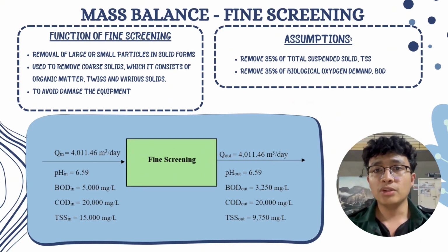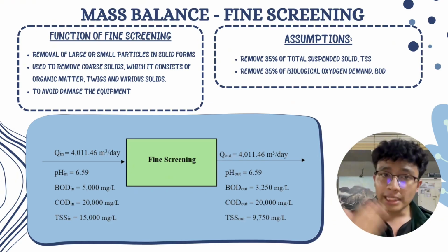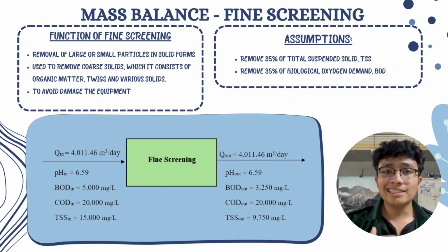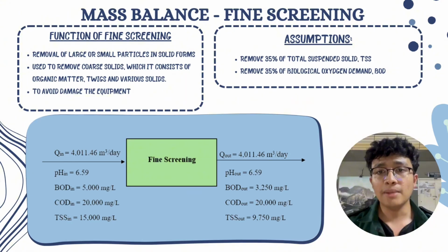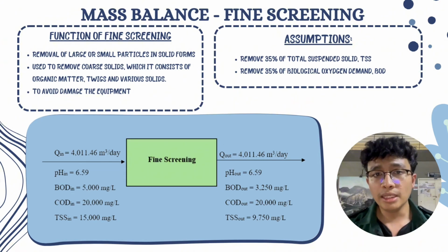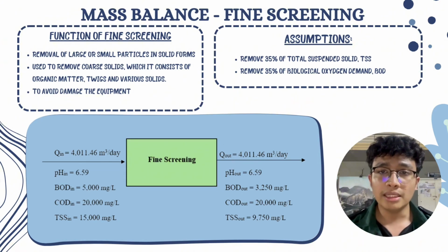Today, I will be focusing on the preliminary stage, specifically fine screening. Fine screening is the first step in wastewater treatment and plays a crucial role in removing solid particles from the water before it moves on to the next stage. These solid particles may include organic matter, suspended solids, and debris that can damage equipment like pumps and pipelines. By removing this material early, fine screening helps improve system efficiency, reduce maintenance costs, and extend the lifespan of treatment